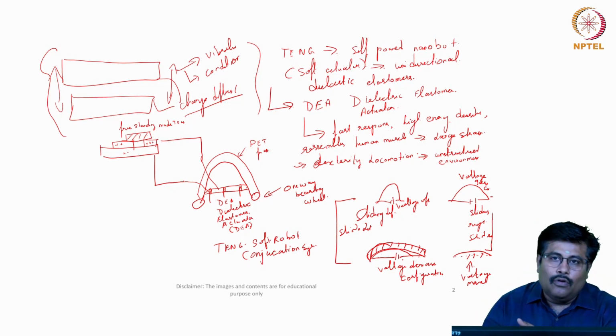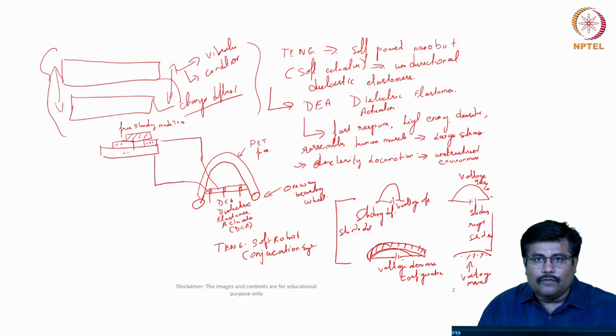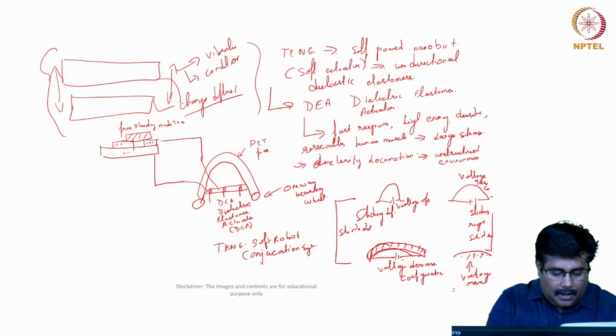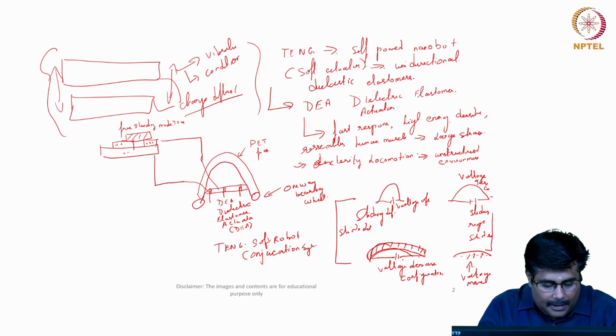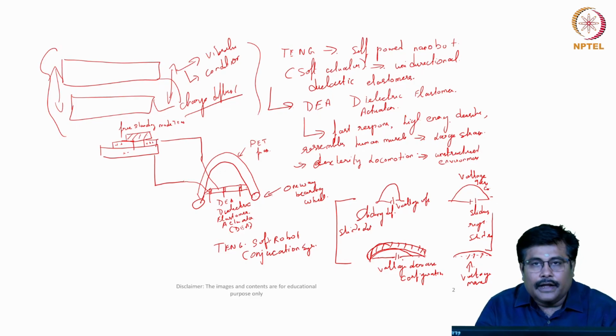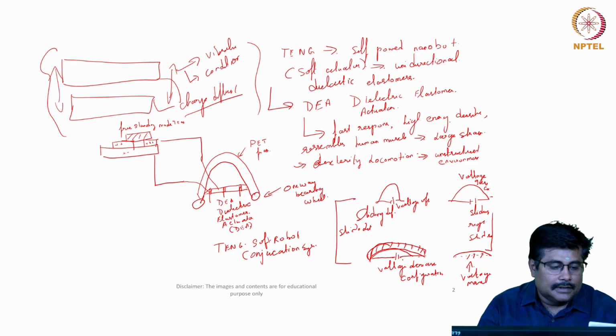A freestanding mode TENG is designed and connected to a soft robotic structure. In the freestanding TENG, the moving component can slide freely on the fixed two substrates. Since the mobile layer is electrode free, it eliminates the electrostatic shield effect that leads to creating a high charge in the system.